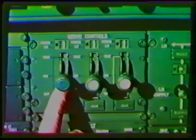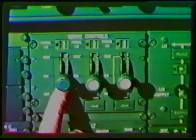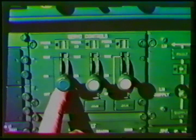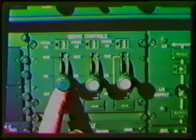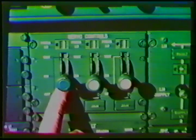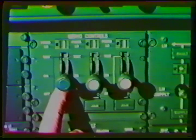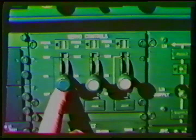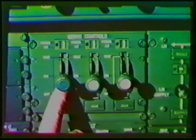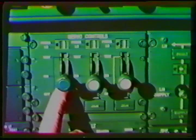On the pilot's overhead panel is located a servo controls module. The blue servo control lever is pointed out here. The lever operates the servo control shutoff valve through which are supplied the units powered from the blue servo control manifold. The subject shutoff valve is represented on the blue system schematic being shown. It is labeled Servo Control Selector. Note the components powered from the servo control manifold.